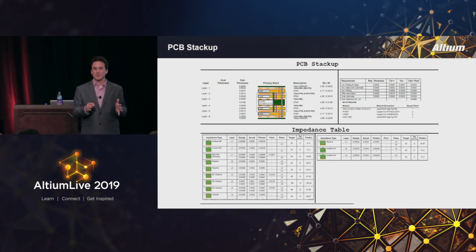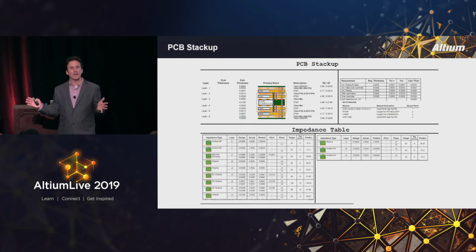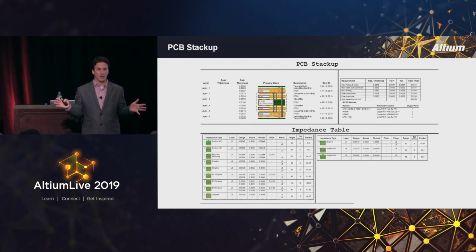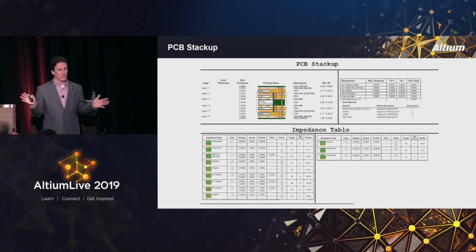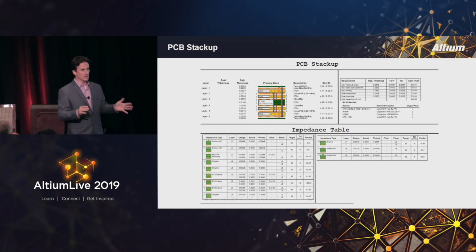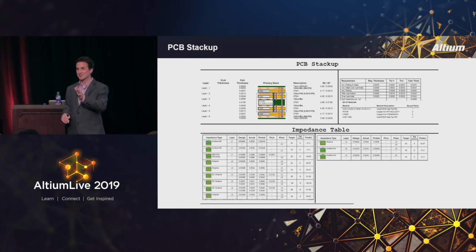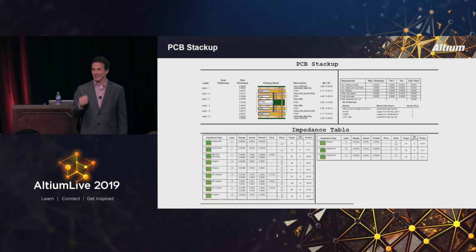One of the hardest stack ups for me is a 4-layer board. You can't get around it. There's no ideal way to do a 4-layer board. The Xbox is a 4-layer board, right? Right. Look at what is on an Xbox. There's every high-speed interface. So, we want to obey design rules, but they got it done. And I know they put a lot of engineering into that. They did, but they also didn't put power and ground on 2 and 3. Yeah. They distributed power with signals, and believe me, they put a lot of time into this.